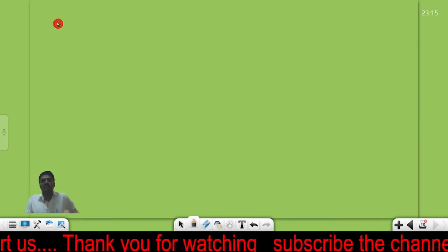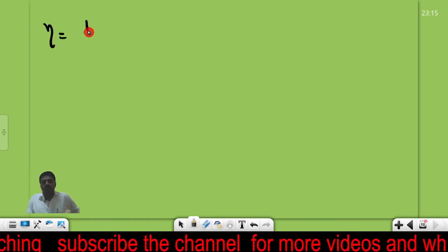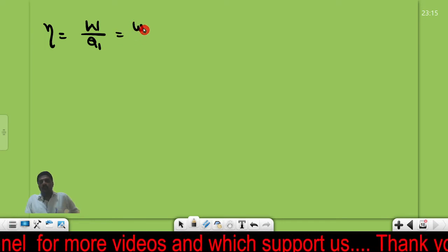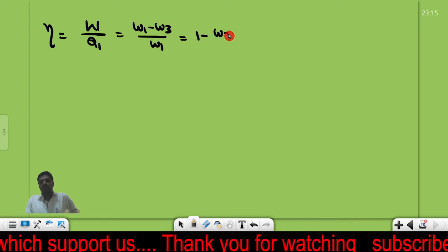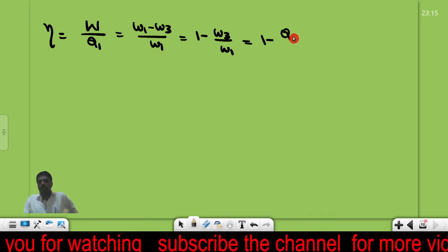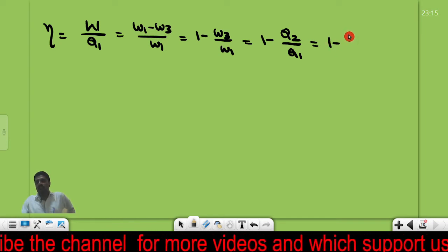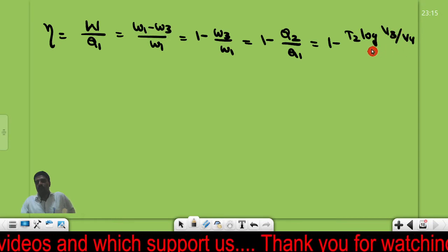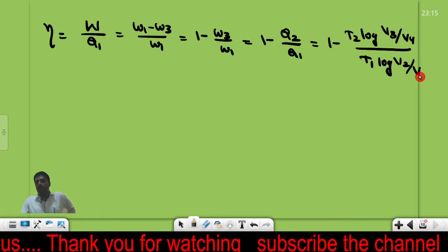Then if we write each and every formula, eta is equal to W divided by Q1, that is equal to (W1 minus W3) divided by W1, that is equal to 1 minus W3 divided by W1, that is equal to 1 minus Q2 divided by Q1, that is equal to 1 minus T2 into log of V3 divided by V4, divided by T1 into log of V2 divided by V1.